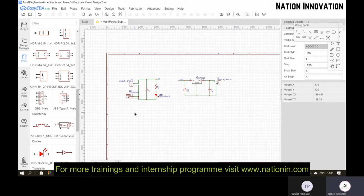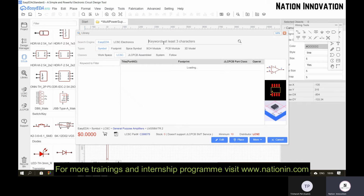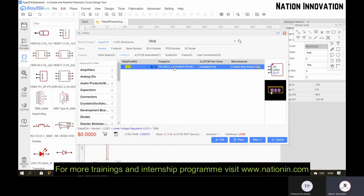Okay. Now I will go for a 7809 voltage regulator. For that I need a 7809 IC that is not there in your library. So you need to find it in your global library. Just type 7809. This is the 7809.